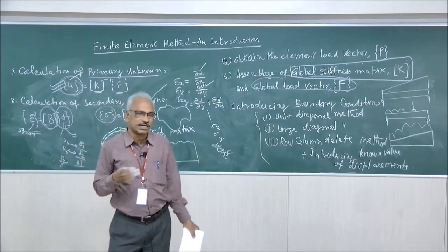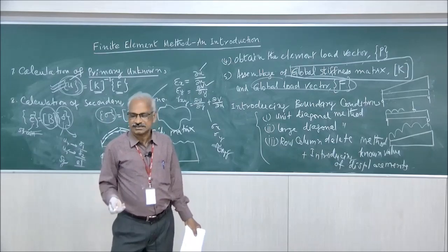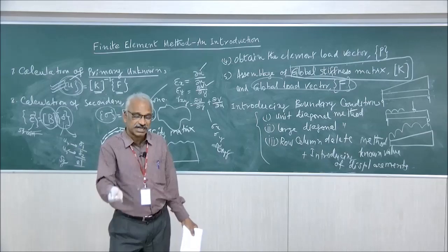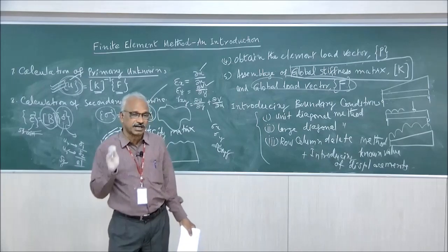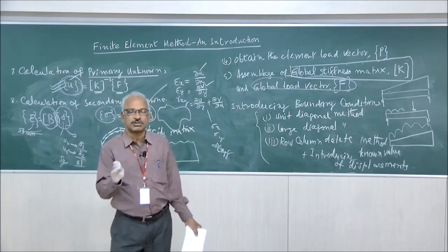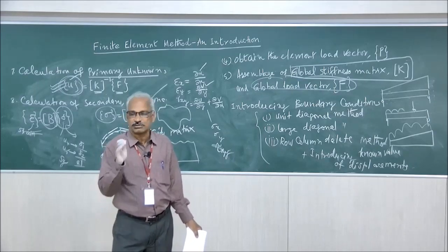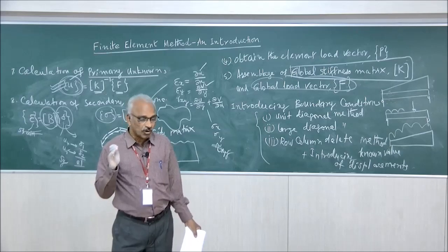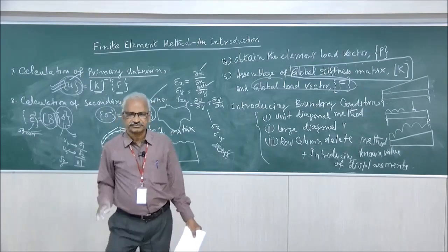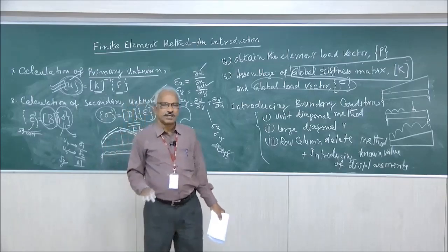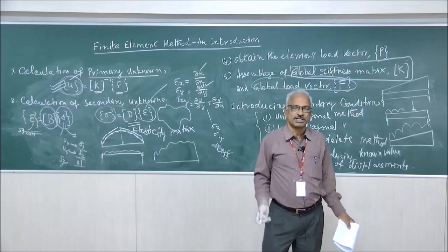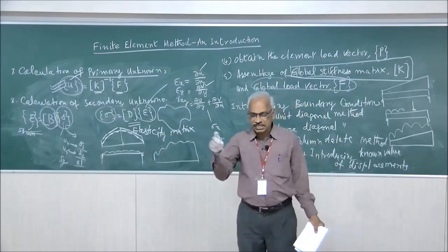For known problems, you just apply. You find out whether it gives the correct results, or what is a mistake on your part, or what is a mistake on the software part. That you have to properly analyze, confirm that this is how I have to introduce the loading, this is how I have to introduce the boundary conditions, this is how I have to divide the structure. Like this, you confirm by applying to a known problem and then go to further solution, because there are many softwares available in the finite element library.